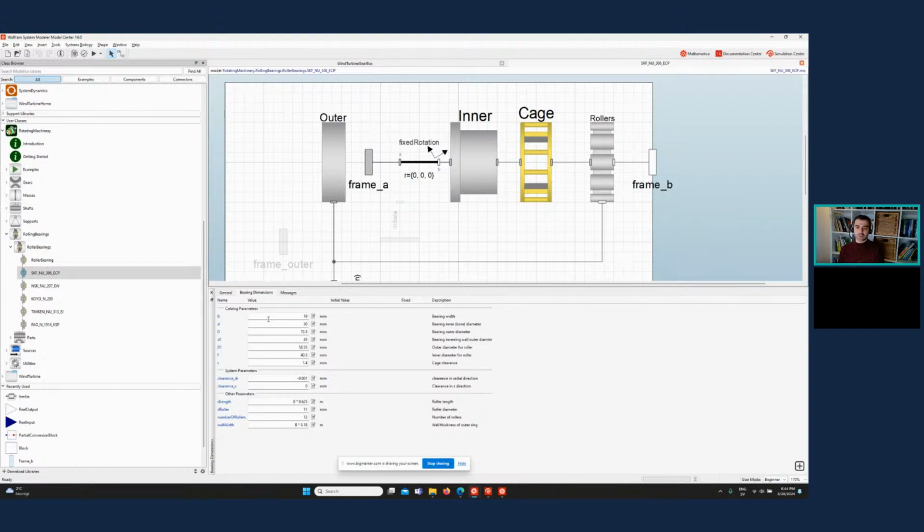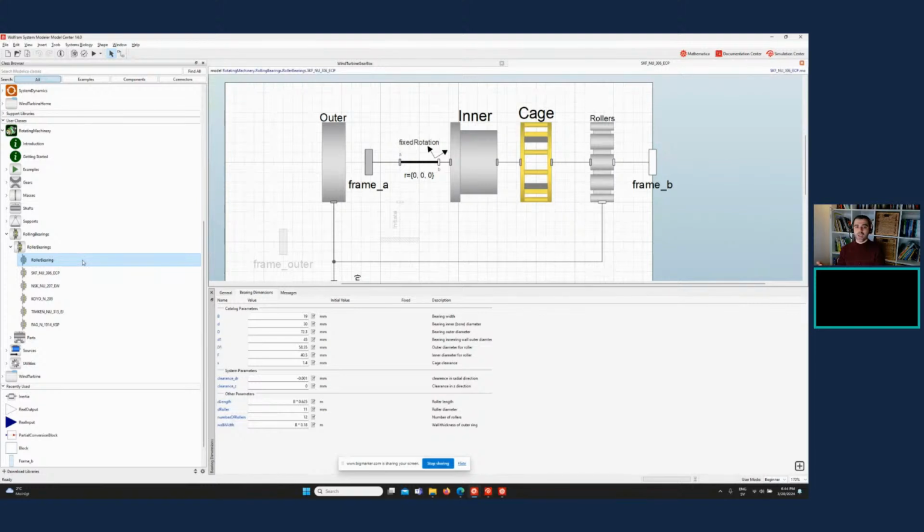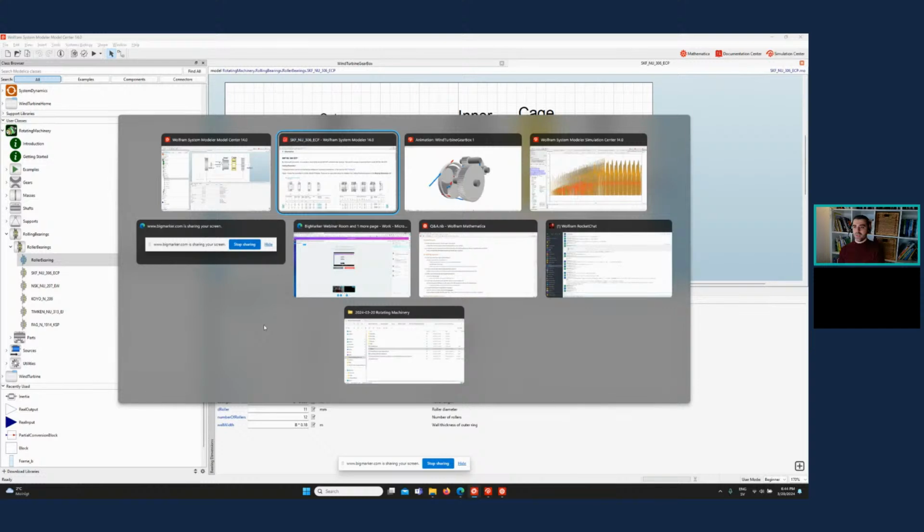You will go to the catalog, go to the documentation and figure out how to read these parameters from the manufacturer. After reading those, you will set those parameters to get your specific bearing, and then you will get your custom bearing. If you don't have any of the bearings among the five we have to show, you can just follow the same workarounds, find the catalogs and the parameters, and register that.